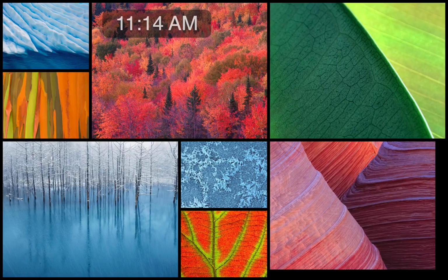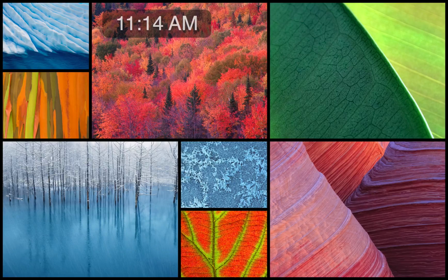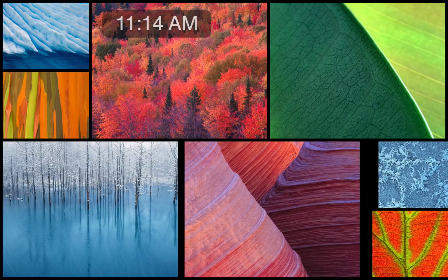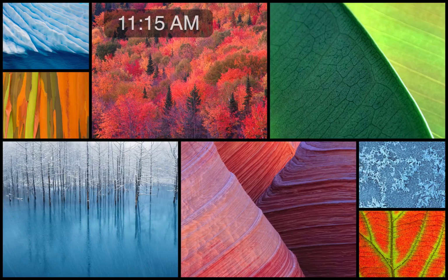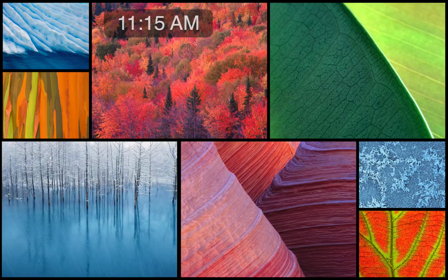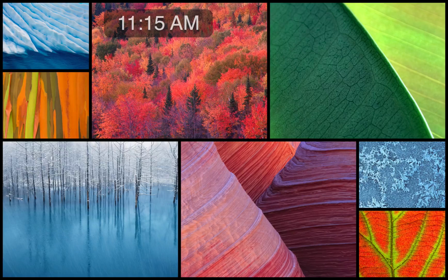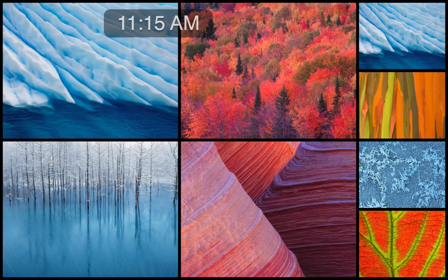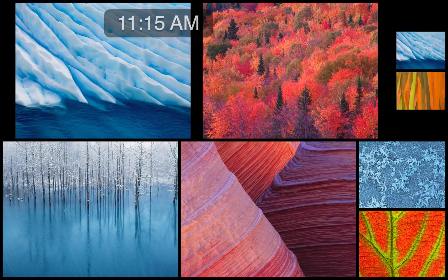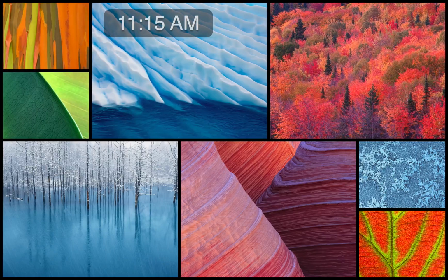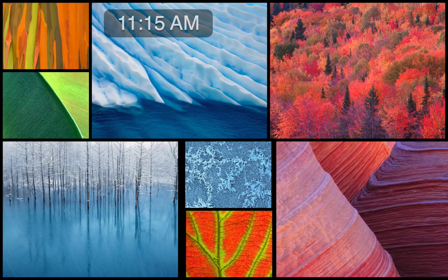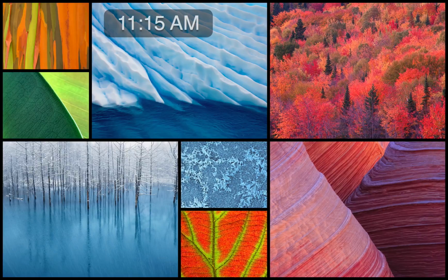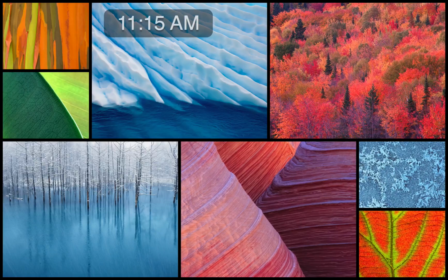I have to manually change all these to 2x4s, and then I have to manually align them. And then I'm going to manually put this column in. But I'm going to change this column to a 4x4. So it's not here, so I'm going to go to architecture, I'm going to go to component. We talked about this the other day. I'm going to say load family. Okay, what happens is it pulls up the U.S. Imperial Library, which comes with your program. And then you go to structural framing. I guess you could go to structural columns. But I usually go to structural framing.